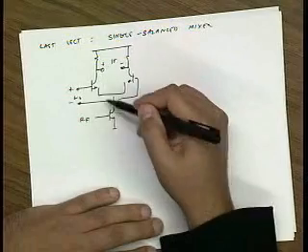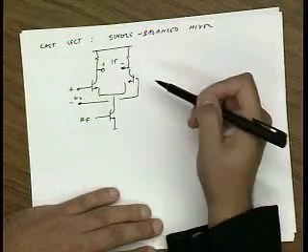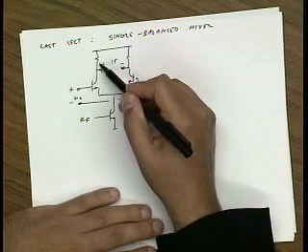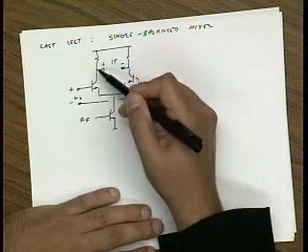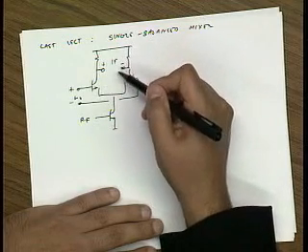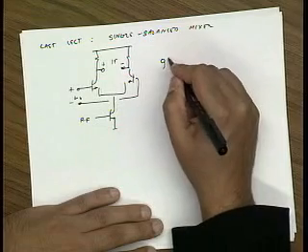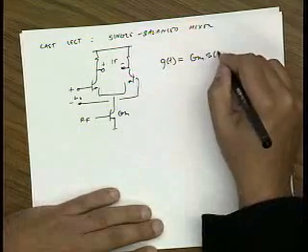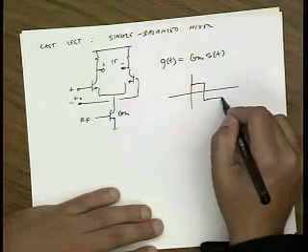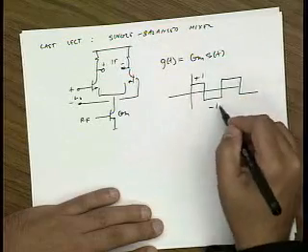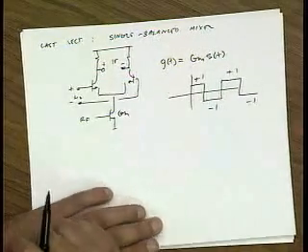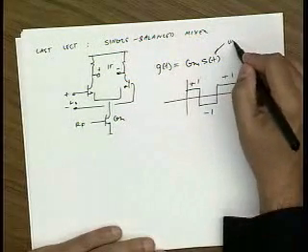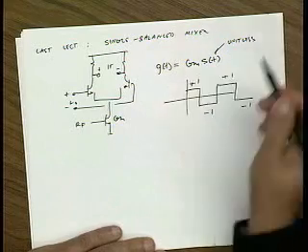Okay? Now, because the output is taken differentially, again, the circuit operates just as before. We swing our current either to the left or to the right, depending on the magnitude of the LO. If we swing it left, this side is positive, this side goes negative. If we swing it right, the opposite happens. It looks like now we're multiplying our constant GM of this device by an S of t, which goes between plus and minus 1. S of t is unitless, and this is a regular GM.